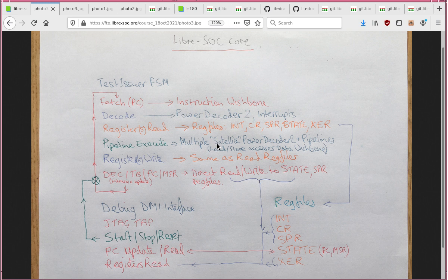And thanks to using Python, we can subset those by the fields that are needed in the columns and subdivide them for the rows, because the main decoder decodes every instruction, but it only decodes enough information to identify the registers to be read, the register to be written, and the pipeline to which the instructions should be farmed.